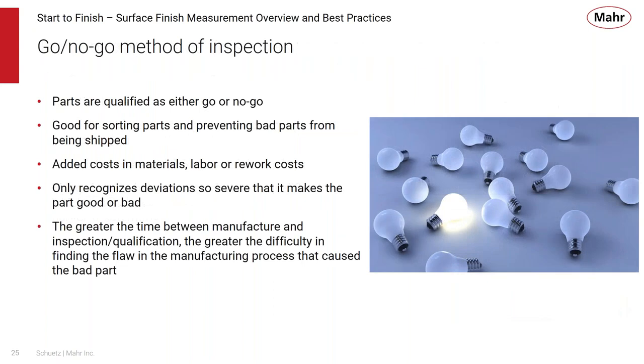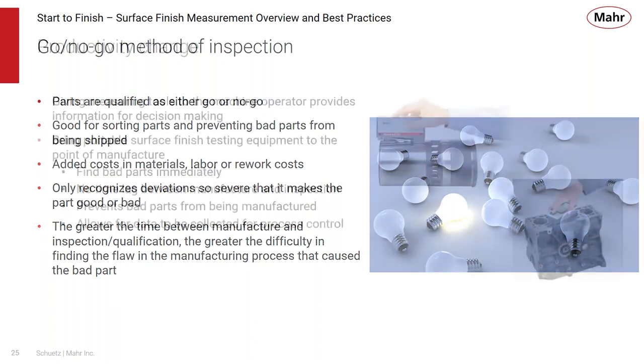And it's really a no-go method for inspection. The parts are qualified as good or bad, but it does nothing in terms of preventing bad parts from being manufactured. There's lots of cost associated with that, and it only recognizes deviations so severe that makes the part good or bad. And of course, like I mentioned, there's that lag time between when the part was manufactured and when it was inspected.